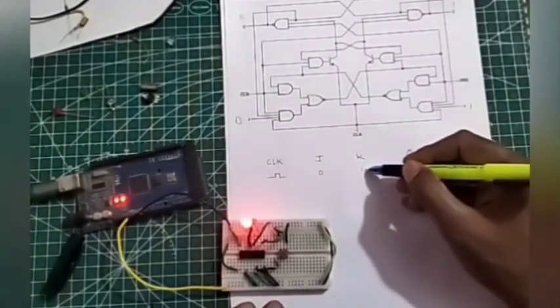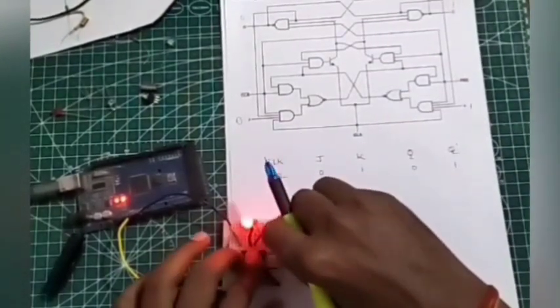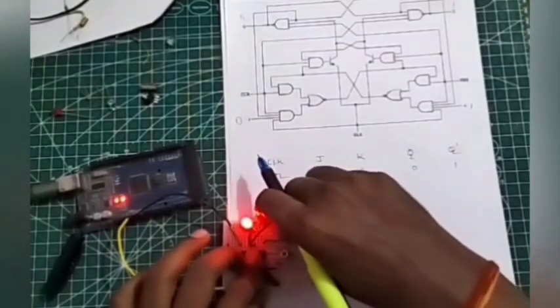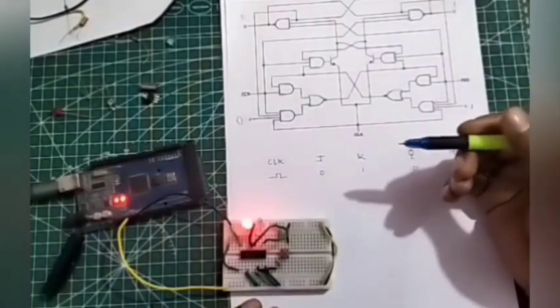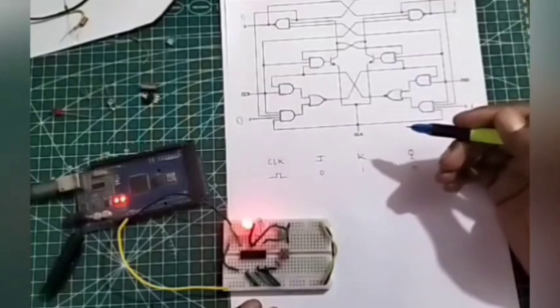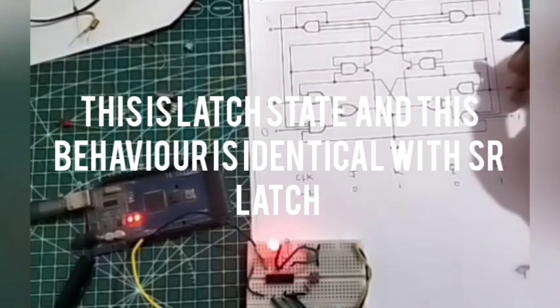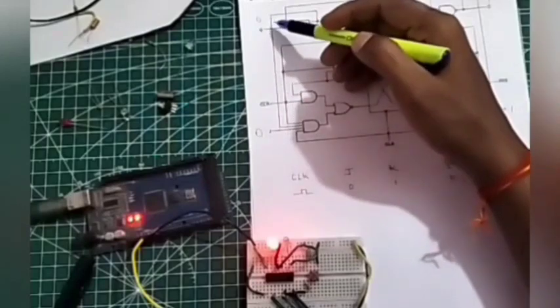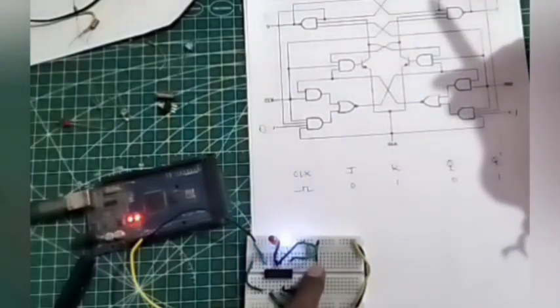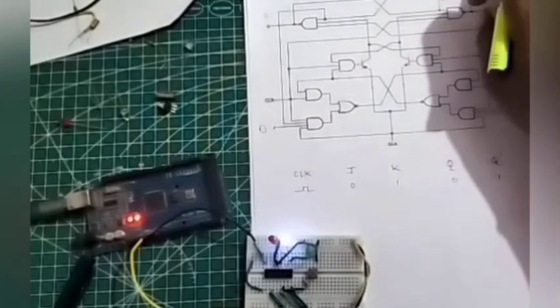Now we'll make K high and J 0. So first of all, we'll make J 0 and K high. So state will not change until and unless we are giving the clock pulse. As soon as I give the clock pulse, the state will change. So Q complement will become high and Q will be 0, giving the clock. See, now this will not change at all. You can see that. Okay.